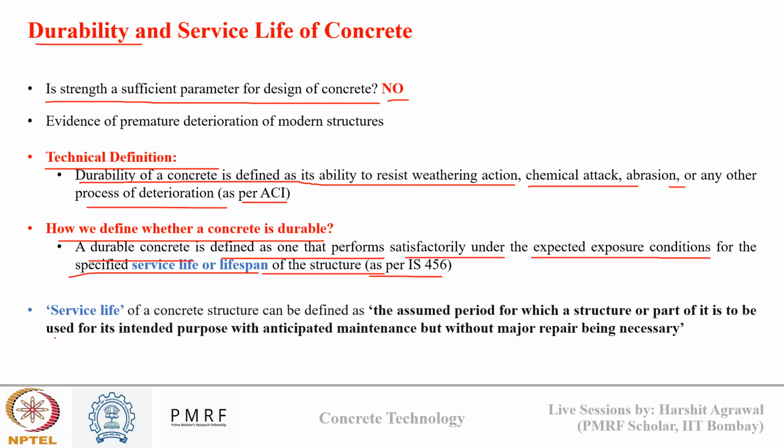Okay, so if you see, I have highlighted one word on this slide, that is service life or lifespan. So it's not like I have prepared a concrete and now it will last for a lifetime. No, concrete will naturally degrade over time, and this natural degradation is what we consider during the design of concrete in terms of service life. Okay, so service life of a concrete is nothing but an assumed period for which a structure or a part of it is to be used for the intended purpose with specific maintenance but without any major repair requirements.